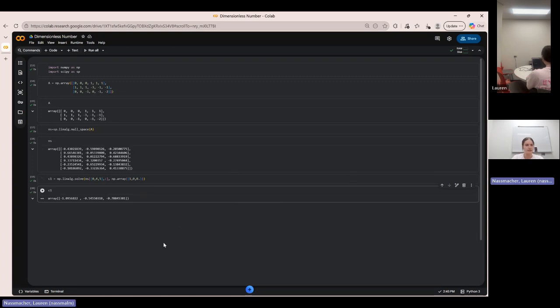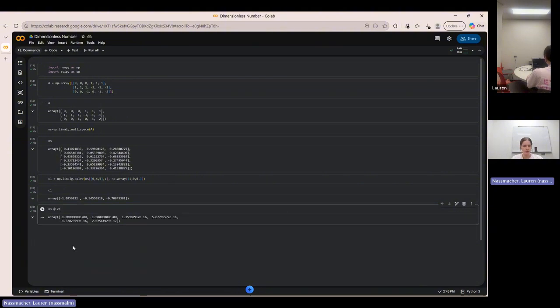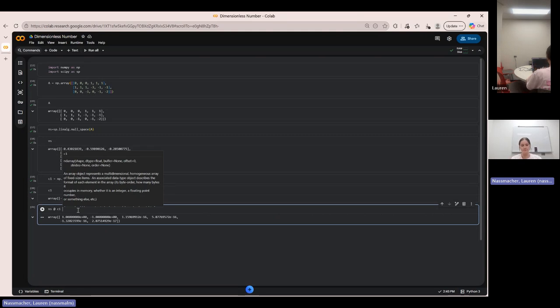These are the numbers you should get from there. We want to create the dot product from our null space. And that dot product is going to get us these numbers. Now, what do these numbers mean? Well, it's a great question. As before, we talked about that Buckingham Pi method, and we had our pi 1, our pi 2, and pi 3. So each of these numbers denotes an exponent that goes to each variable: length, pressure, viscosity, velocity, diameter, and density. The first one is length.